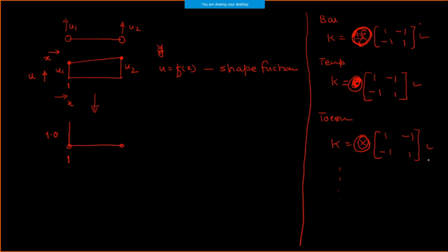So the stiffness matrices remain common, but their constants are going to vary, or the multiplication is going to vary. So when I want to keep this common and only change the constant, how can I do it? I can have a unique shape function for each node. That's what I'm going to give as normalized shape functions, which is also called a natural coordinate system.